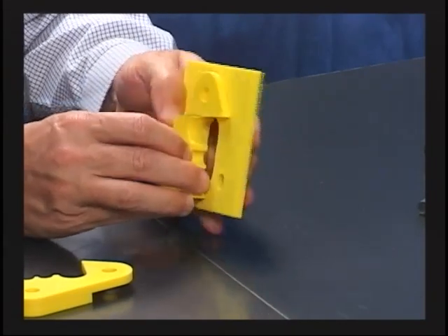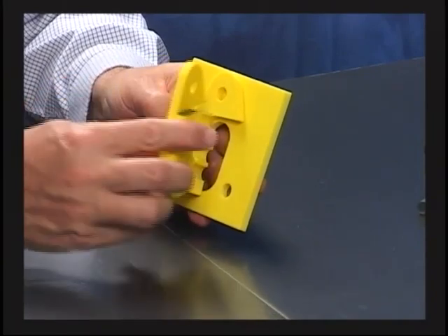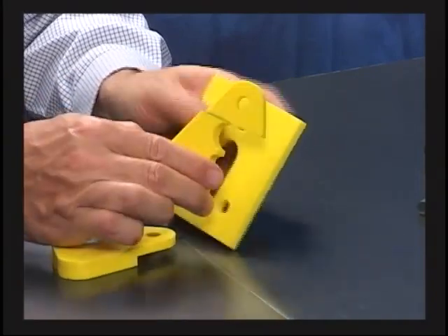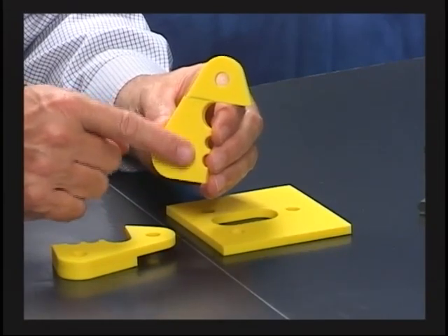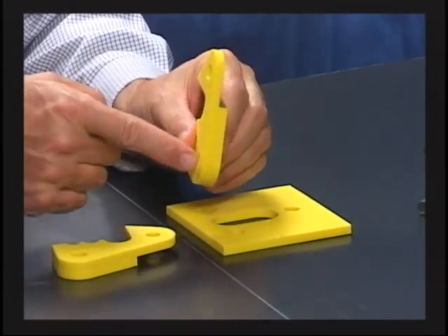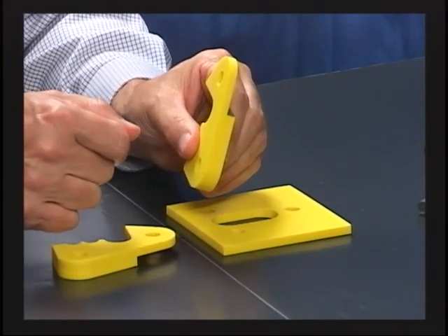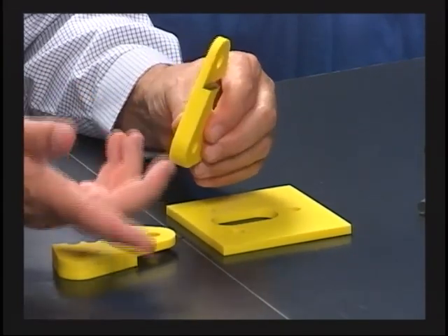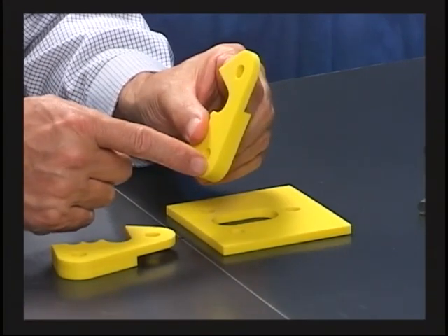Now you might say, well, yeah, that part mounts up, but this one, when it goes on, mounts on the other side. Why didn't you pick the front face? Well, I guess I could have picked the front face just as well as the back face, but you notice I saw the back face being longer, so I selected that as my primary datum. If I have a choice between a long one and a short one and I can't decide, I would just go for the long one. So that was my primary datum.